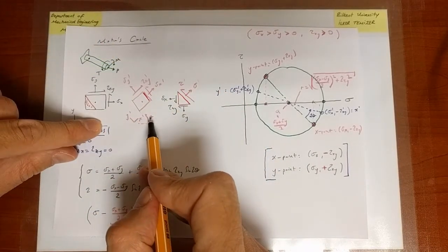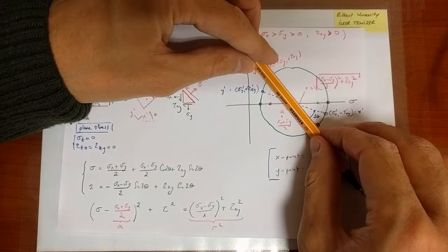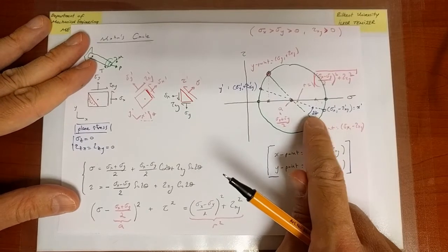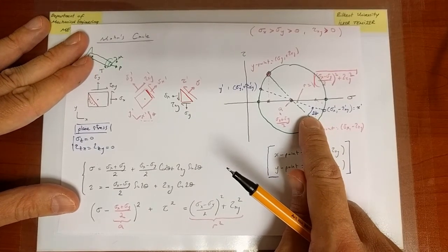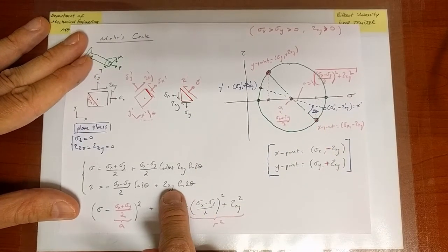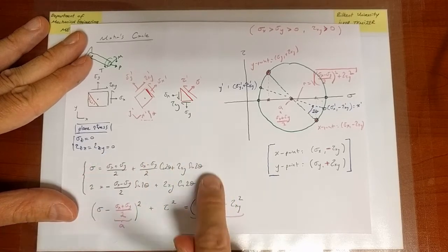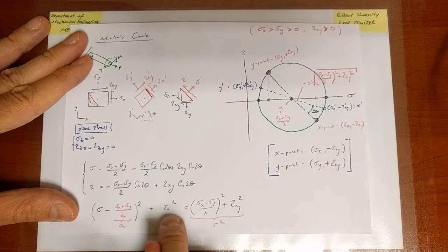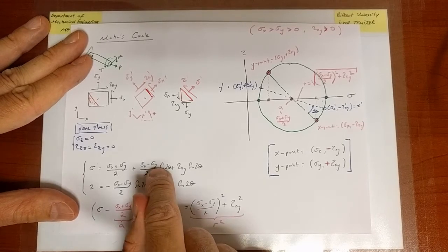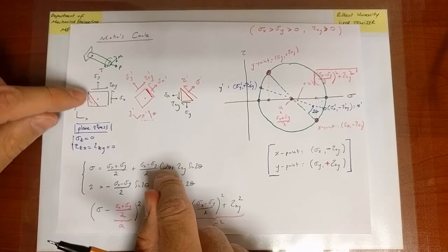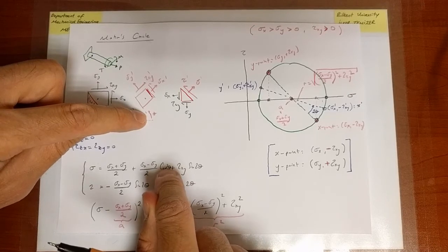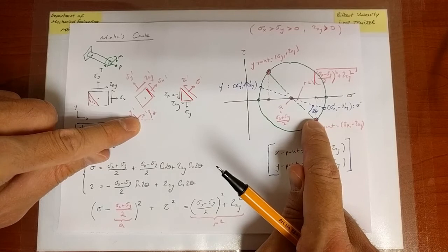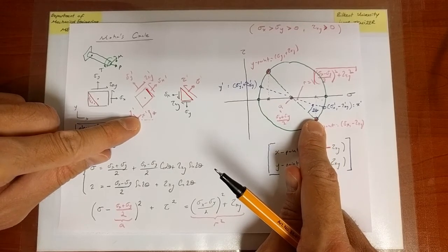I've rotated through an angle theta, and now on the Mohr circle, I'm rotating through an angle 2 theta. Why is there this factor of 2 once again? Well, ultimately, it has to do with the fact that the equations always involve a factor of 2, and I derive my interpretation of the circle from these equations. In the equations, a rotation of theta reflects as 2 theta, and therefore the rotation of theta on the original picture reflects as a rotation of 2 theta on the Mohr circle.